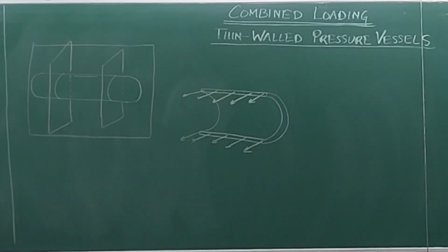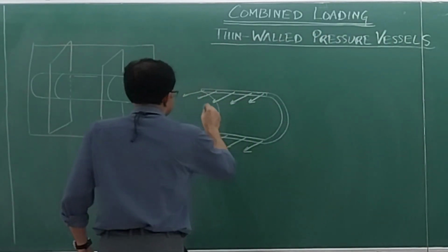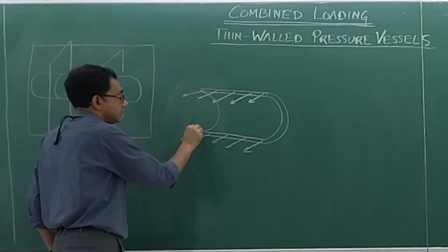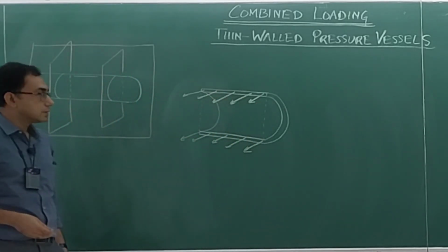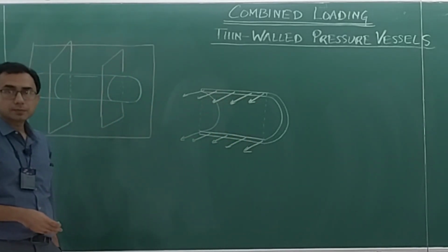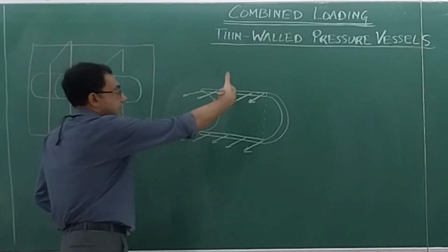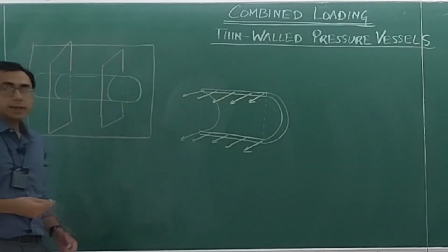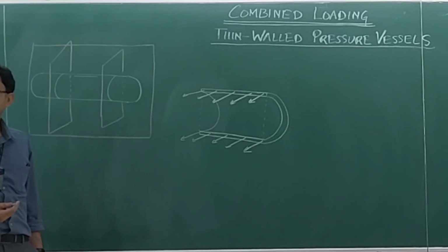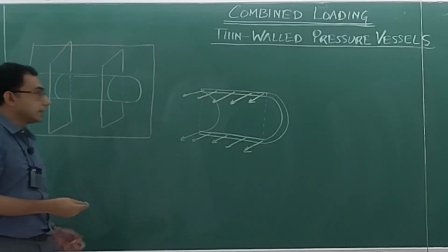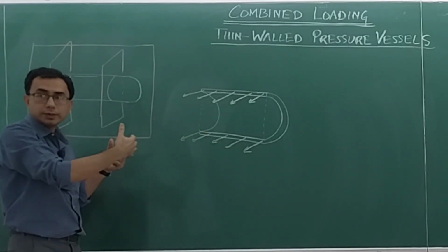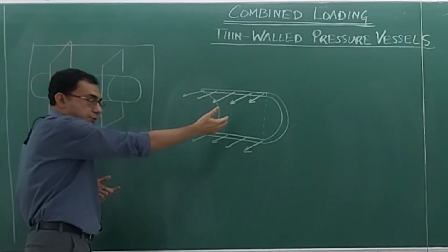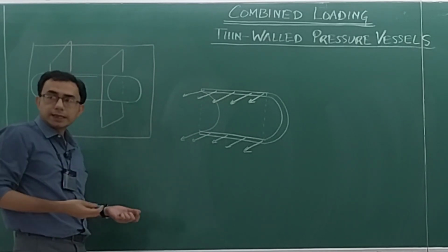And over here in the inside, okay, please understand that this portion, this entire half cylinder, is filled with the fluid. Okay, so if I just consider this plane, then what kind of forces are being exerted on that? You will have the force due to the pressure of the fluid, which is the counterpart of it. So when you have cut it, there is another part which I have not shown. That part of the fluid is exerting pressure on this part. Okay, so it is like a free body diagram.